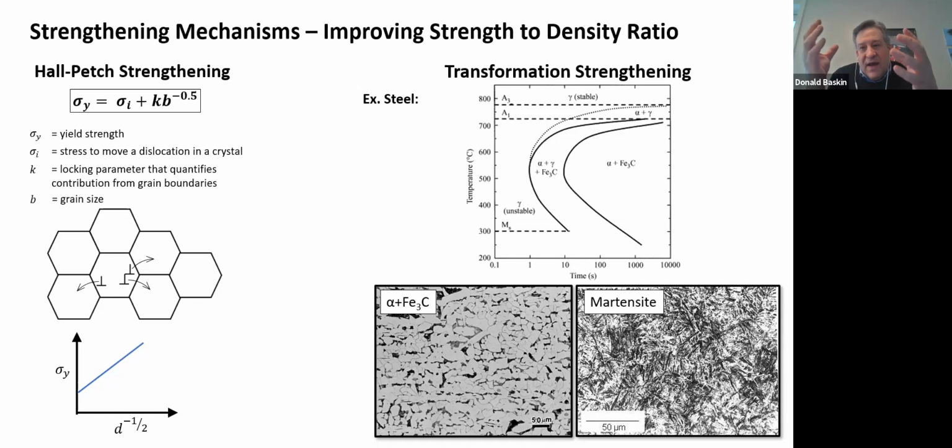And then as the nickel evaporated, it would get close to this cold finger, this copper cold finger, and then the nickel particles would freeze instantly when they hit this cold finger. Okay, and then they would freeze in this tiny little size here, this tiny little grain size. Okay, and so on Monday he was very happy because he took a hardness test,